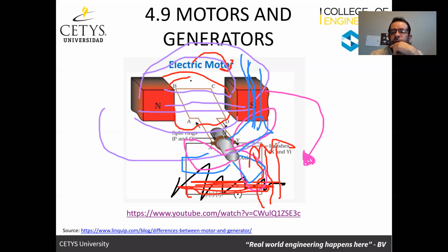There's going to be a current generated because of the magnetic field, because of the induction effect that we just saw in Faraday's law. So the same principle of the motor, but configured differently, where I have a physical force moving a rotor along where there's a coil along a magnetic field, is going to induce a current, like Omar said. Well, that's the principle of a generator.